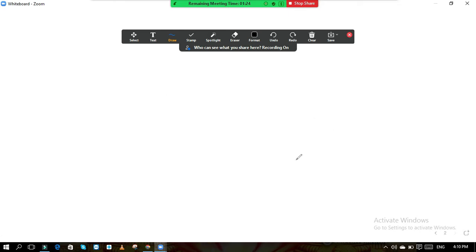म्हणजे काय होते ते बघा. Now suppose this is the slab. Okay, suppose this is the slab. Now when you are casting the slab, at the same time if you cast the beam, so this is the beam below the slab. At the same time if you cast the beam, this becomes a monolithic construction, because at the time when you are casting the slab, at the same time you have cast the beam.